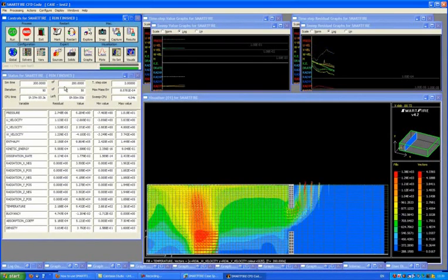So we've now reached the end of the simulation, and you can see from the visual that the flow is fairly well established. The plume is leaning over slightly due to entrained air from the window, and the spill plume has developed outside of the window, spilling out into the extended region.